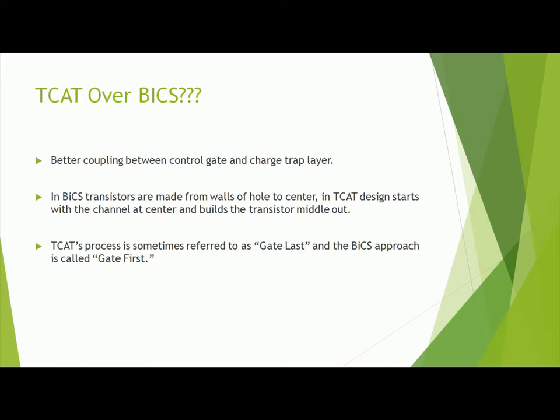The TCAT process is also called gate last because the gate is formed in the end, and the BiCS approach is called gate first because the gates are formed first.